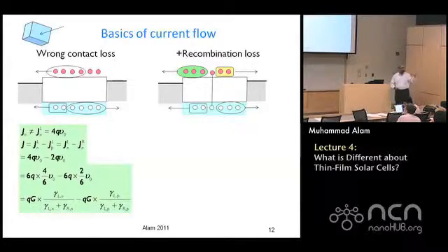If I have 2 doors, then the probability that I'll escape through that one versus through this one is normalized, so that's it. So I'll write a formula which is something like this: the generation rate, times the probability that the electrons escape through the right contact, the proper contact, minus the probability that the holes escape through the wrong contact, and that gives me the total current.